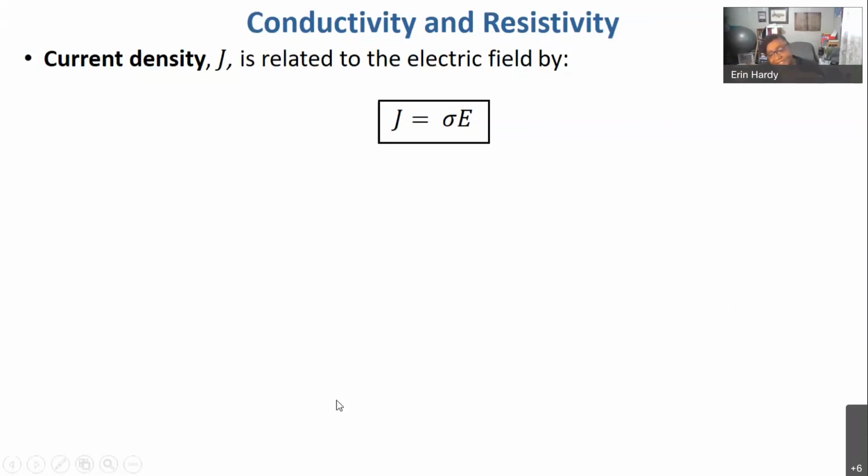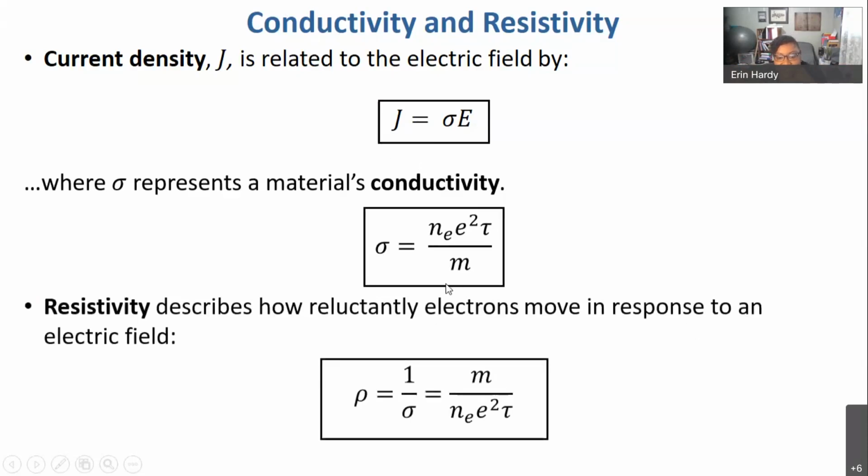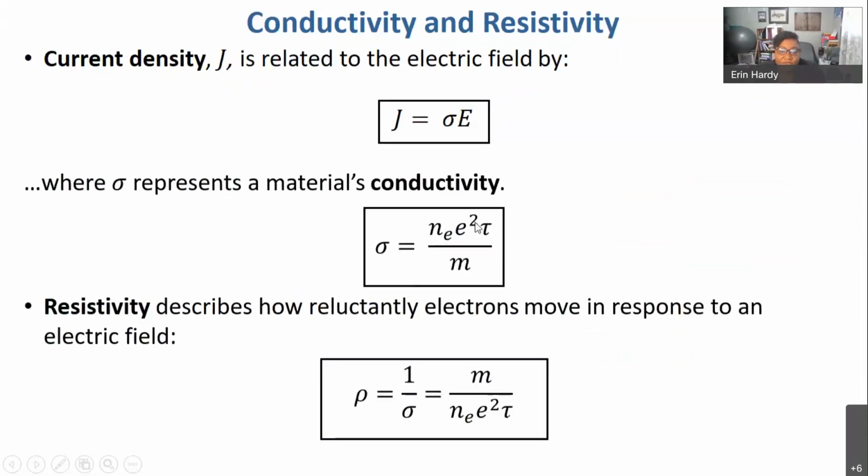So we know that current density is something that we can evaluate by taking some kind of external measurements if we know the size and shape of a conductor. However, we also can track current density in terms of the conductivity of the material and the electric field strength acting on it. So this J is exactly the same as the one that we saw a few slides earlier, where this conductivity has a unit that is maybe not introduced in the slides here, but it's a little interesting.